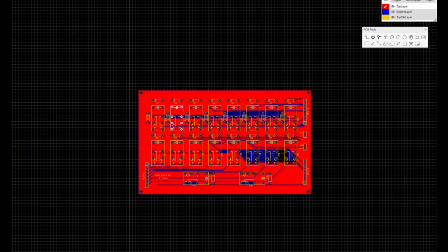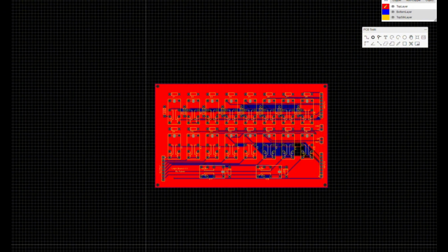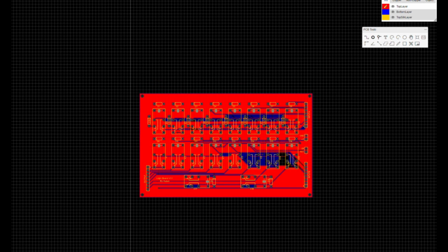There are diodes here because they all connect up, and without that it causes back feeding. It goes back round here and through this line, which then feeds to all the other ones, and they're all open, so it feeds back round. Yeah, it's not a good idea, so diodes are needed. On the current version I've made, which I've got printed, I forgot to put these in, so I have to get that reprinted. And these are always the diodes, which are always needed. That's basically how this board works.